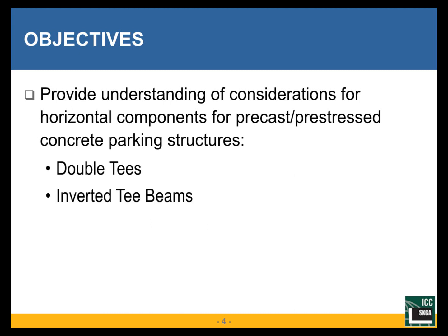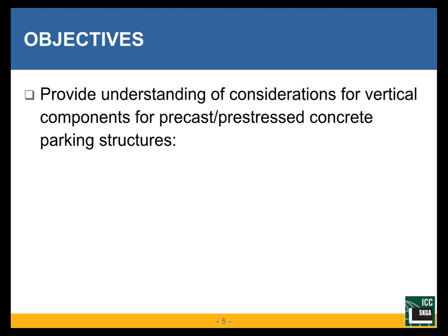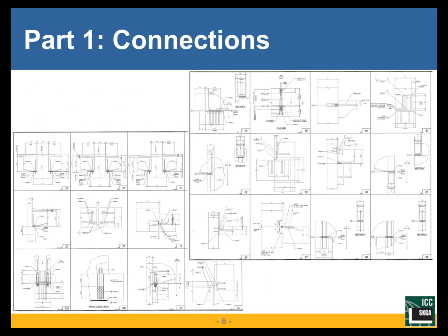We'll look at double T's, inverted T-beams, spandrel beams, and flat slabs and stairs. Finally, the third part, we will talk about the considerations for vertical components for precast prestressed concrete parking structures. We'll think about interior columns, exterior columns, ramp walls, shear walls, and stair walls.